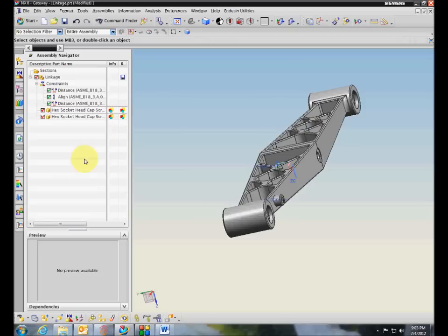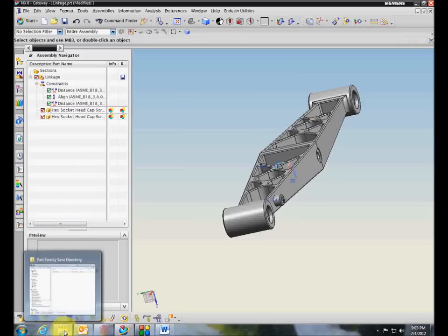So you can also edit the part families as well. You can create your own parts, and you can make them adjustable the way these parts are. But I wouldn't recommend making those parts part of the NX machinery library. I would keep the two separate because it will make updates and whatnot easier. And in a future article, I'll go through how to make your own adjustable parts and create your own directory where you can save those things.